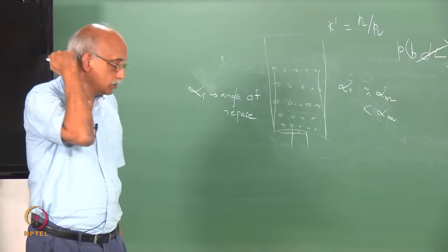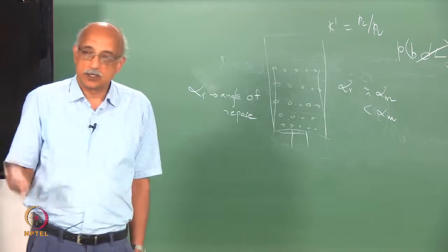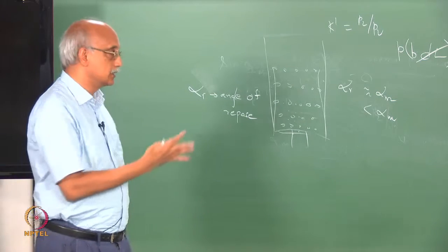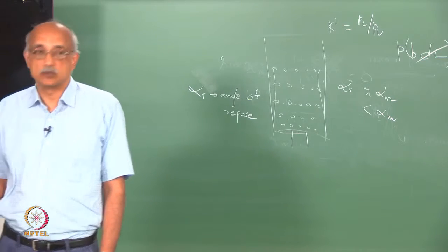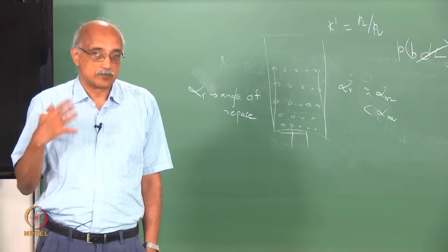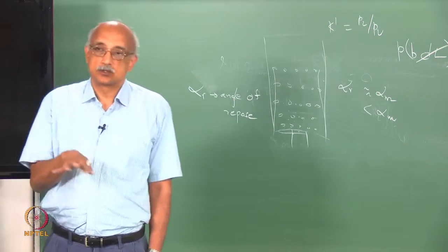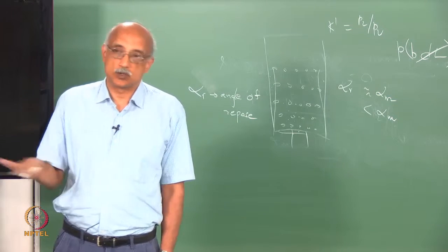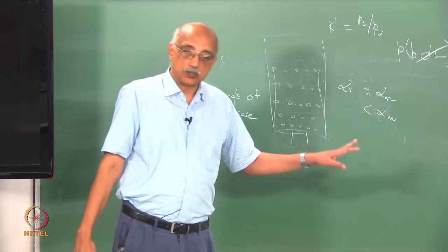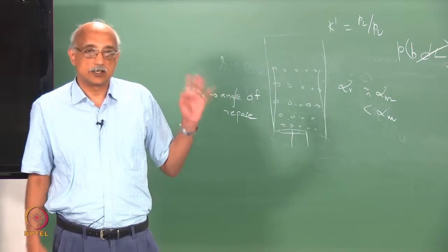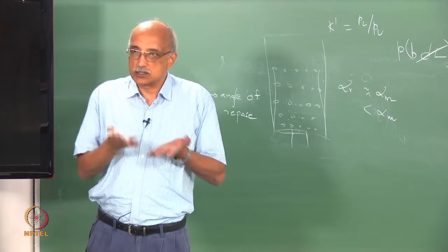So, for good flow, what you would like is a low angle of internal friction, which also results in a low coefficient of internal friction between the layers as they start to flow, which again means there will be less temperature rise, there will be less energy input to achieve the same amount of particulate flow and all that. And you also want an angle of repose that is fairly high. You want the particle layers near the walls and the container bottom to be ready to leave as soon as flow sets in.